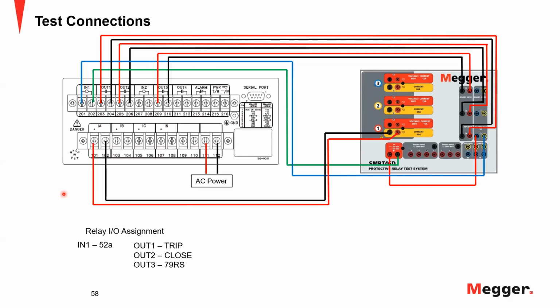So you can configure these timers to get your reclose times and trip times, and then you can decide the start and stop of each timer using these conditions. And these conditions can be started and stopped either by change of a state, or you can also do it using the change of a post. It can be a binary input operation.